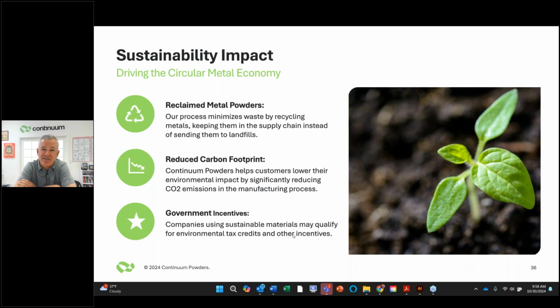The way I discuss it with customers or partners is very simple. If you've got, for example, a MAR-M 247 fan blade that you need to run in one of your industrial gas turbine engines, and that has been BER'd, beyond economic repair, and a repair process, if we get a hold of that MAR-M 247 fan blade, which is maybe fatigued or timed out, there's no better pure alloy than that actual fan blade to then go create the same alloy now in the form factor of powder.